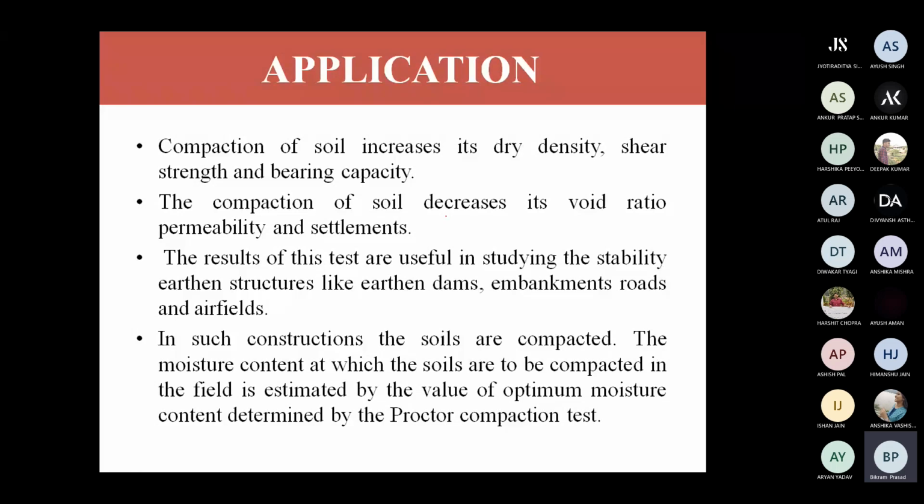In such constructions the soils are compacted. The moisture content at which the soils are to be compacted in the field is estimated by the value of the optimum moisture content determined by the Proctor compaction test.